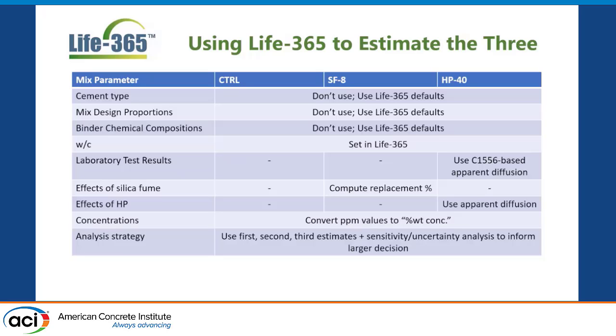So just understanding, I guess, that when we talk about parameters for this or any tool that we're holding in our hand, understand you may have variation due to coarse discretization that dominates over 10% differences in other, finely tuned input parameters. Exactly. Even the numerical precision of the numbers that are held in memory by, in this case, the Java compiler, can cause variations if you're not careful about where you're using that numerical precision. If you're dividing by small numbers, that kind of problem. You have to be very, very careful with it.